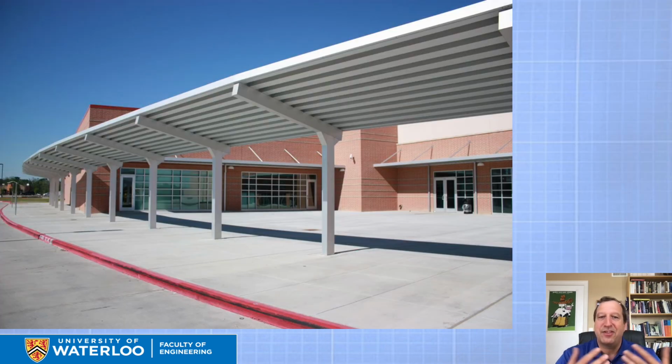And then at this point, there's no way that we can say that this is being resisted by anything other than the vertical cantilever post. There's one post and all of the loads, both gravity and wind loads and lateral earthquake loads, all being taken by a moment connected post. And we usually see it for these types of architectural purposes where it allows a special type of building.